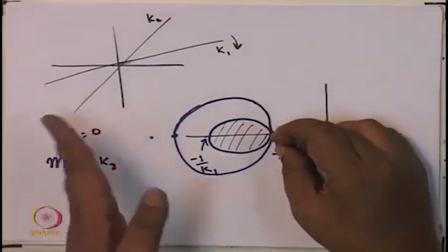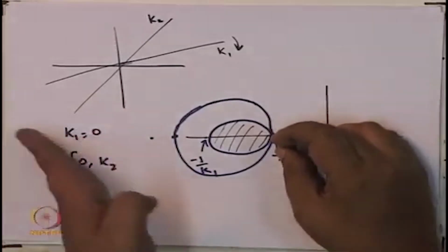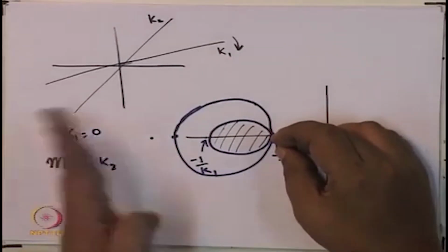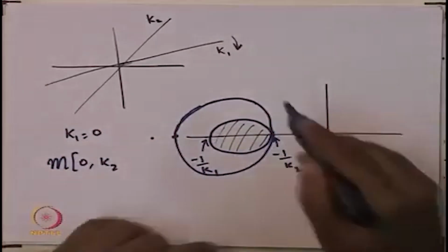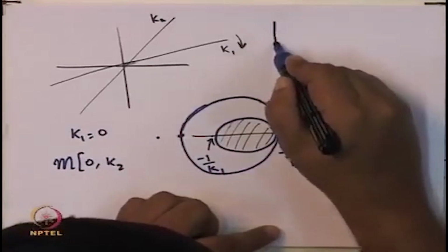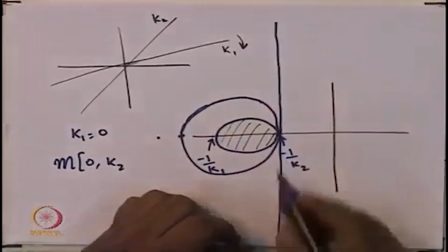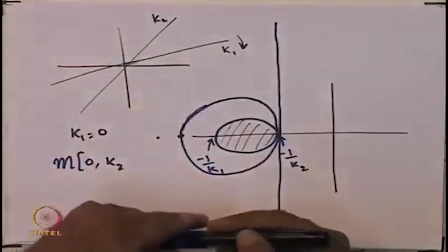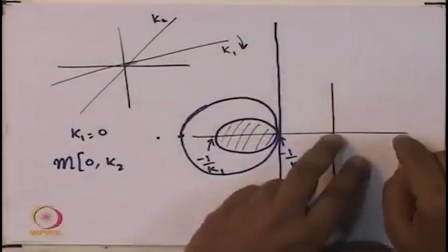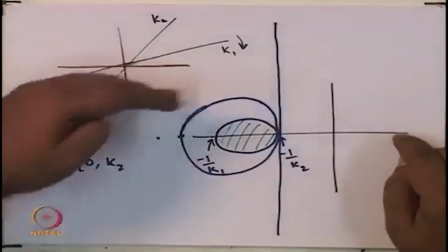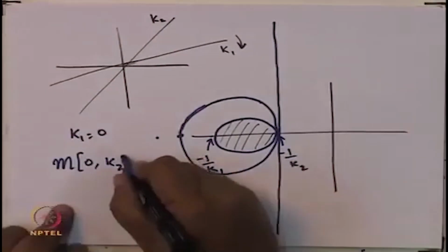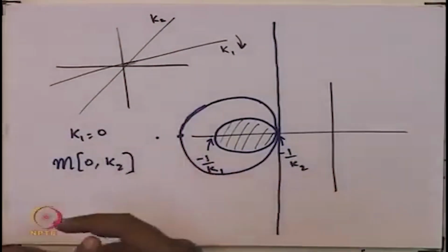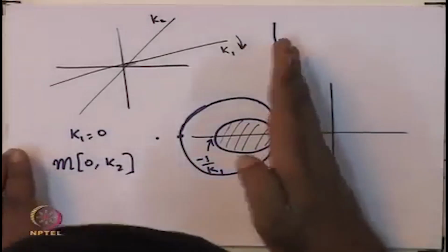So, it's gone real far off, and then the circle criterion essentially tells you that that particular circle is everything to the left, which means the Nyquist plot in this particular case, if you are looking at k1 0 and k2, that means if you are looking at a nonlinearity like this, then the Nyquist plot should lie to the right.